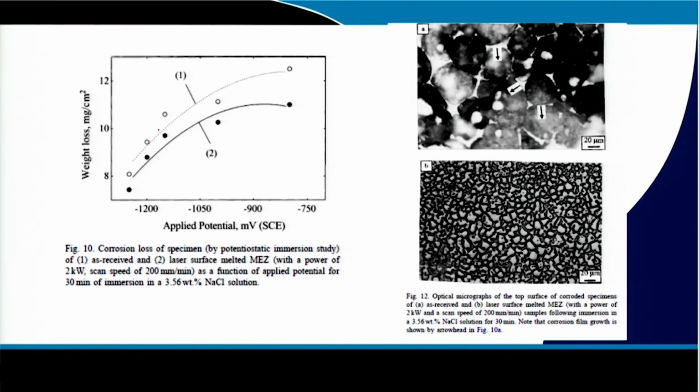So, naturally, whenever you are interested to know the corrosion behavior a little bit in detail, you have to understand the mechanism of the corrosion. This micro mechanism of corrosion needs a detailed understanding of the post corrosion microstructure and also phases. We found out the post corrosion microstructure, and we found that in adhesive structure the corroded film which is forming is highly loose and porous in nature.